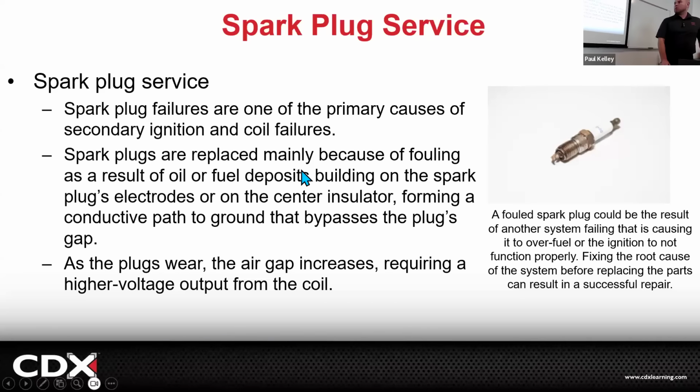The spark plugs also, over time, they wear and the air gap increases. So you know what that means? You know how the spark plug gap is a set number? Well, when you think of a spark plug, you don't think of it wearing out. Nothing's touching it, right? But believe it or not, that arc and arc and arc and that high temperature and fuel and turbulence in there, the spark plug actually will wear the metal away and the gap will get bigger and bigger and bigger. If that's the case, we don't try to bend the gap back up. We replace the spark plug.